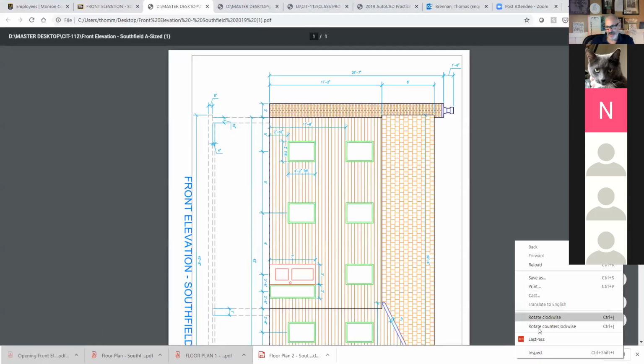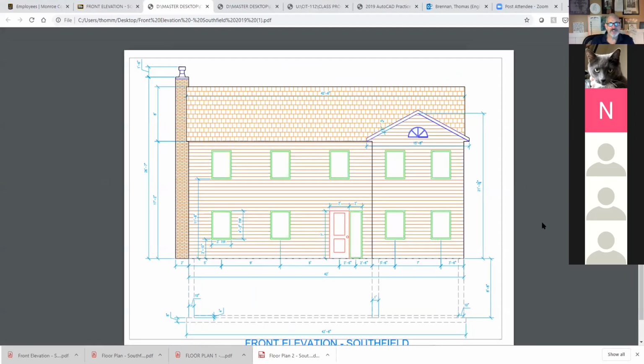Here is an elevation plan. The elevation plan is showing us the same structure, only a front-on view as you're looking at it right from the front. That's an elevation. And there can be interior elevation views, which would mean you'd be looking at the inside of a wall, where maybe the furniture and what the windows would look like and so forth, or an exterior. In this case, this is an exterior elevation. So you're looking at what the structure looks like from the outside, showing you the windows and so forth. Does that make sense? Okay, right. So that's an elevation. Now you will always remember that.